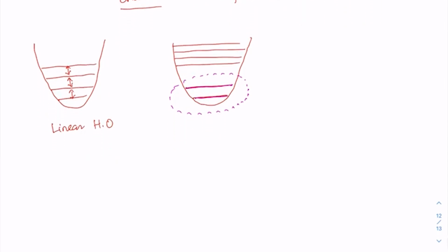In fact, when a circuit is composed of a Josephson junction, we know that the Hamiltonian, which we discussed earlier, has two parts. One is the charging energy part, that is Q squared by 2Cj, and the other part is because of Josephson tunneling, that is generally written as minus Ej cos(phi by phi 0).